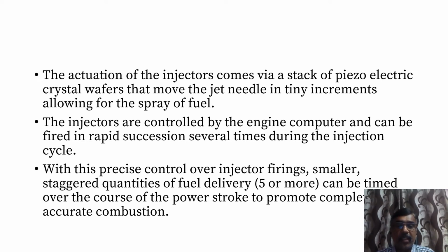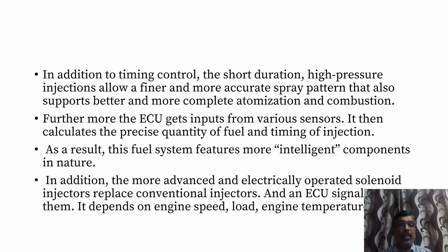The injectors are controlled by the engine computer and can be fired in rapid succession several times during the injection. With this precise control over the injector firing, smaller, staggered quantities of fuel can be timed over the course of the power stroke to promote complete, accurate combustion. In addition to the timing control, the short duration, high pressure injections allow a finer and more accurate spray pattern that also supports better and more complete atomization and combustion.